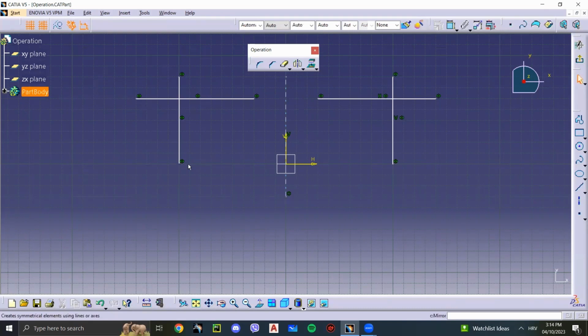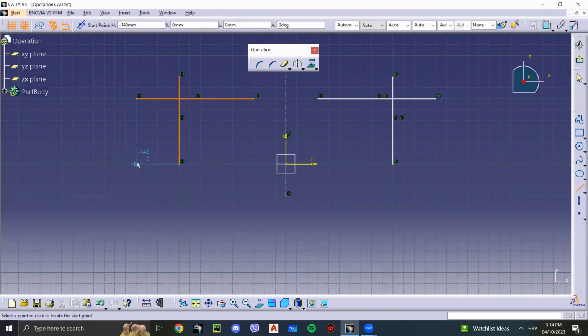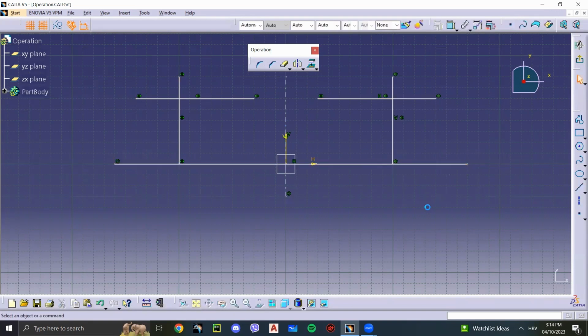Let's say we want this down. We don't have to use an axis line; we can just use a normal line. Actually, wait. Hold the control key on your keyboard and press all the elements you want to be mirrored. Let's say we want these. Then select the mirror command, and select the line from which the elements will remain equidistant. And there we go. It's mirrored.